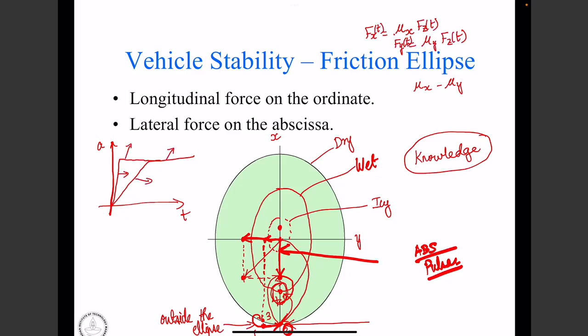So this is an important point. There is a subtle difference between the rate of braking and the extent of braking. You want to go from 0 to 100% braking, let's say in 5 seconds, as opposed to, let's say, half a second. The steady state magnitude of the braking force will be the same, but the way we get there will be different. The dynamics will be different. Any other questions before we proceed?